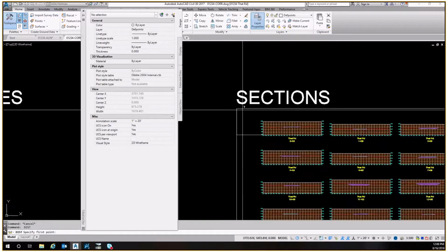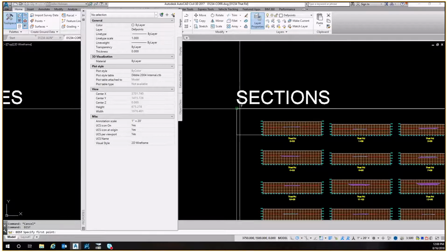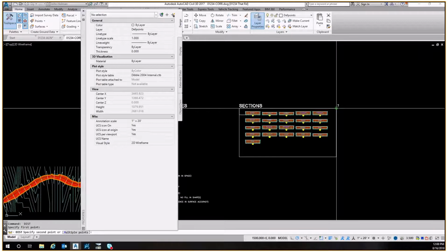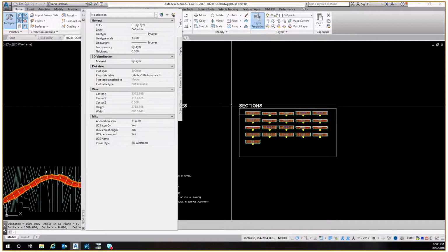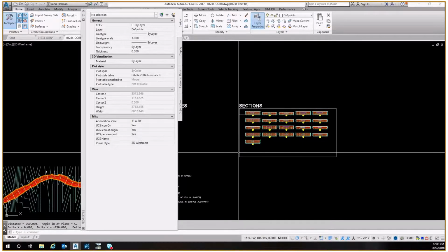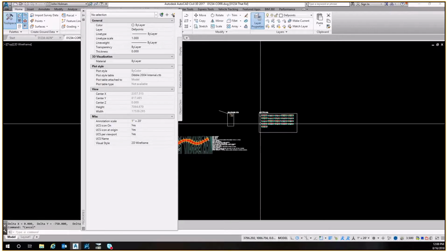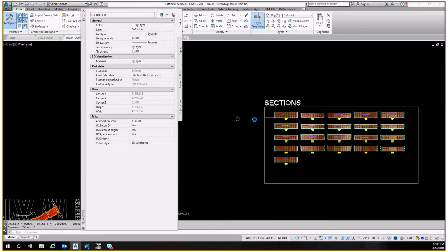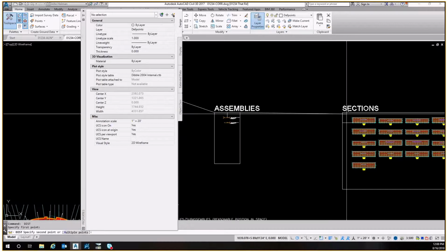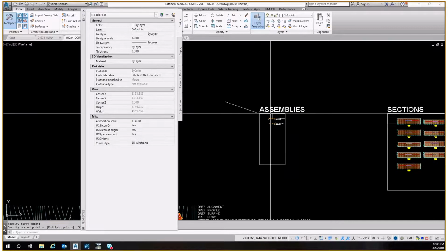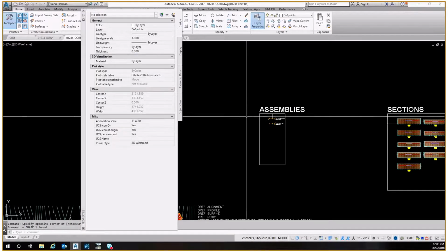Same thing over here. I picked an even numbered XY location, and I drew this a sensible dimension, so that's 1500 feet, and this is 750 feet tall. So all these shapes that you're looking at that are floating out in space, they're not just floating randomly. And these two lines are actually level with each other as well, if you look at that. Try to keep things clean is basically the motto here.